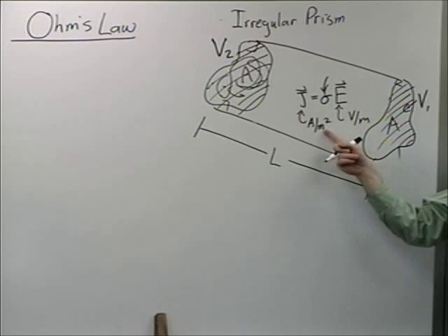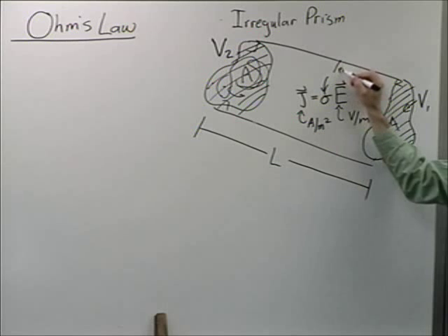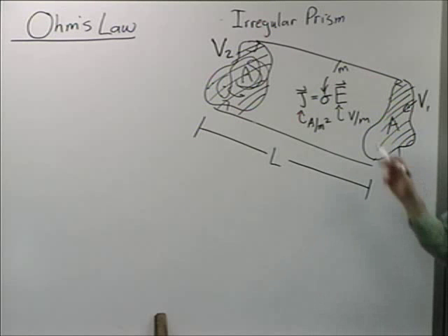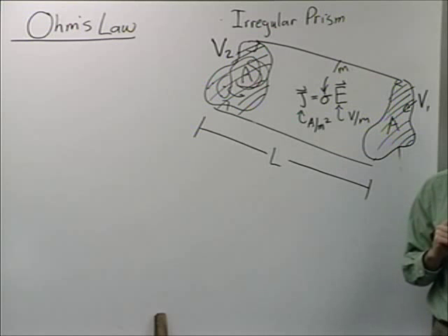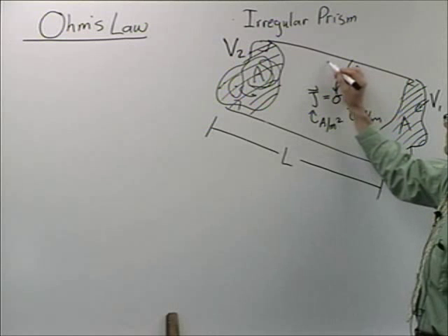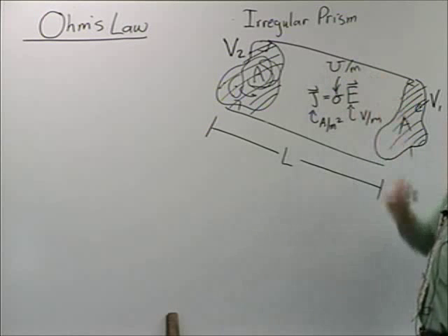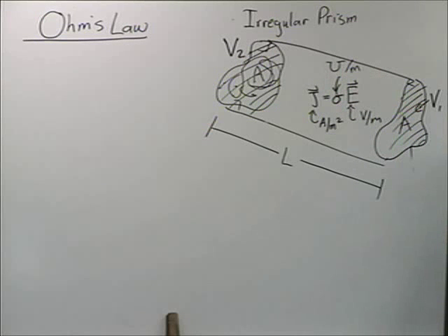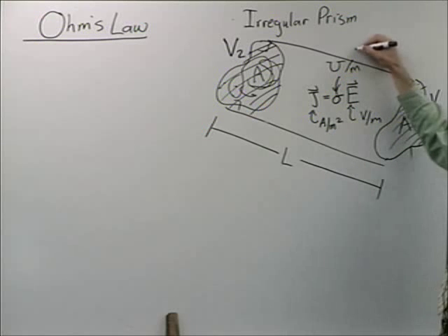Let's see, I need a meters in the denominator, so it's going to be something per meters. And then I've got to take voltage and turn it into amps. So it's got to have 1 over R, 1 over ohms. So I can write that as an upside down omega, mhos. Siemens per meter is the actual definition. And this is the conductivity.